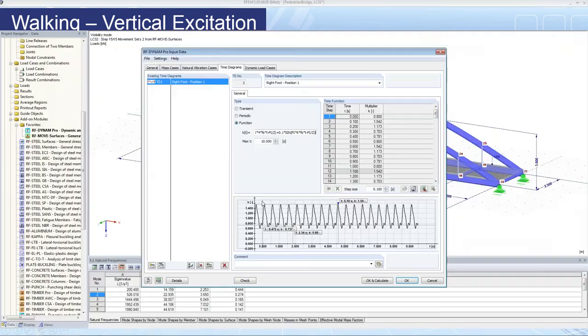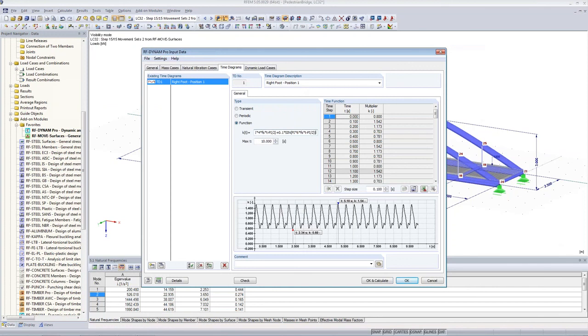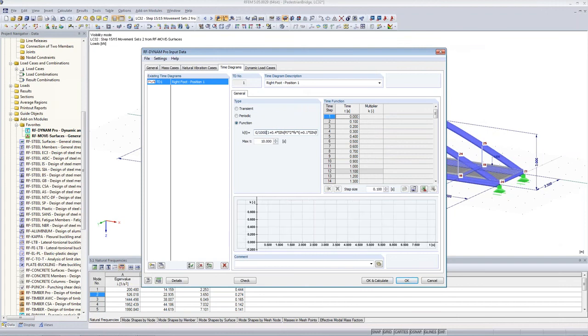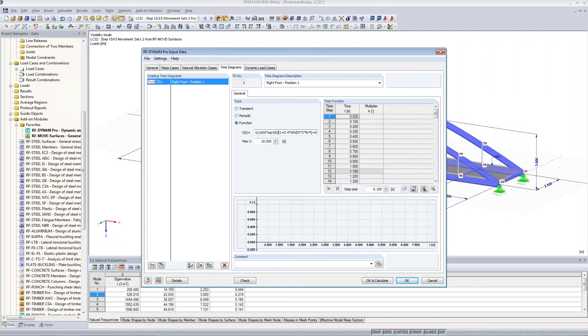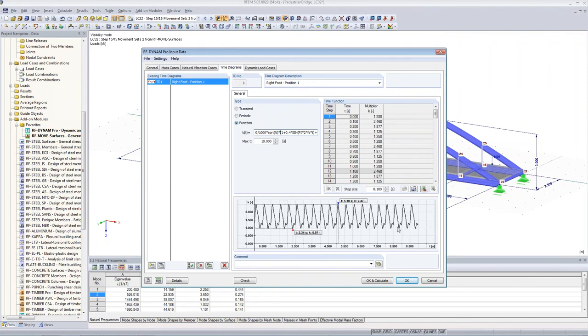Here we have to be a bit careful, because the self-weight of the pedestrian, we entered this parameter in kilonewton, but internally in RFEM everything is used in Newton. So I have to divide my G by 1,000 to really get my kilonewton. This is a bit tricky; you just have to be careful. I have defined 0.8 kilonewton in the parameters, but internally 800 newtons are used. Then I have the square root over n multiplied, and this is the formula I'm finally using.